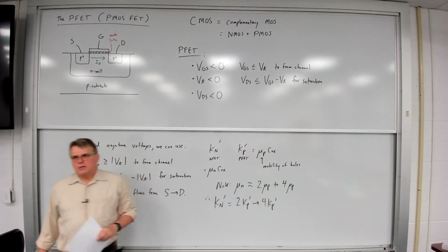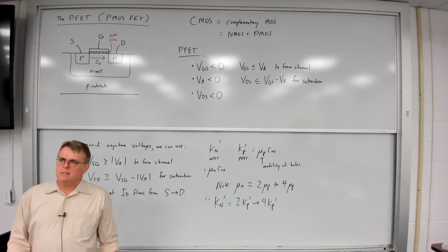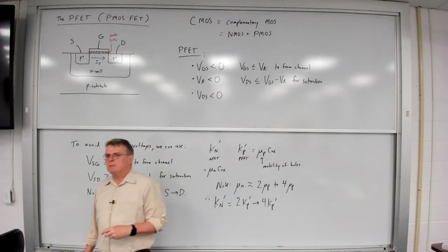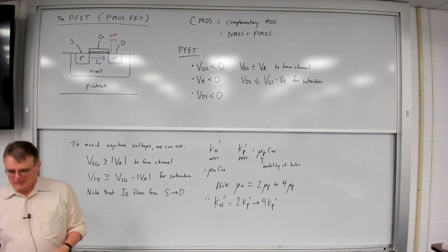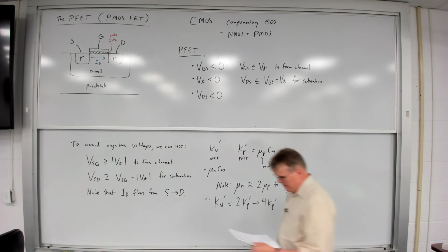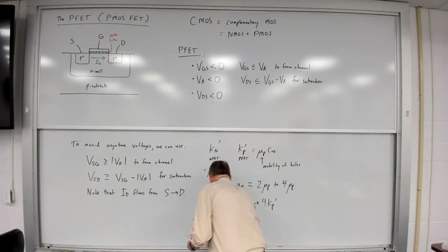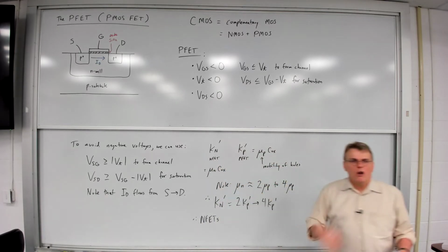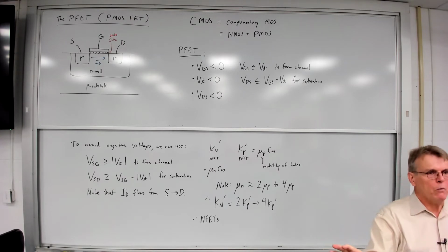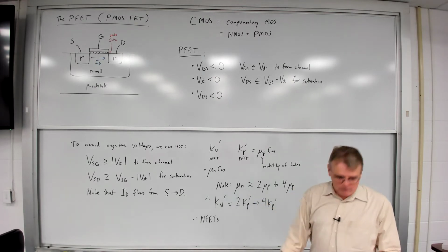Now, some people may ask, gee, doesn't that mean we'd rather use an NFET than a PFET? Well, sometimes it does mean that, but it still turns out that having those PMOS devices is extremely useful, depending upon the circuit you're going to have. All right? But what this tells us is NFETs will generate larger values of drain current than PFETs, all else being equal in terms of geometry and the magnitudes of the voltages.